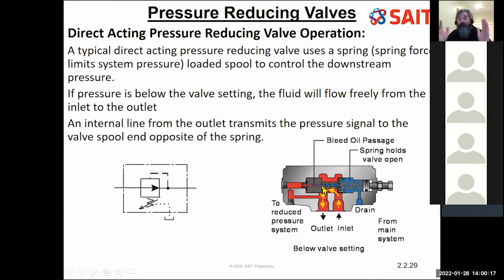I'm going to get a little bit of a balance, and this valve is going to sit at that point where just enough leakage going through the system is going to operate the valve and hold the pressure. If I've got a little bit of leakage in my cylinder, blow by, it's going to be fine. This valve will accommodate that.